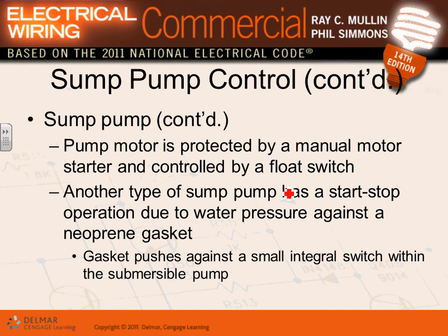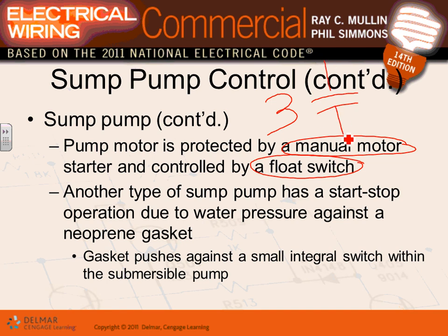Okay, a sump pump protected by a manual controller starter and controlled by a floating switch. They have a magnetic controller, guys. A floating switch is turning it on and off. Here's a magnetic controller, it looks like this. Here's a contact, and there's a floating switch. My floating switch is bringing voltage, say 120 volts, to this coil. When this coil is energized, bang! Now that contact will close. When the floating switch opens, it opens the control circuit. So what controls the control circuit is a floating switch.